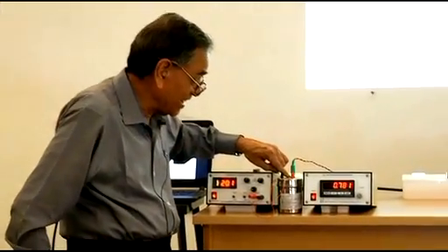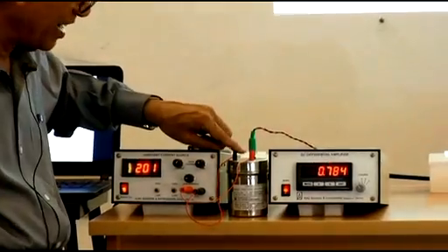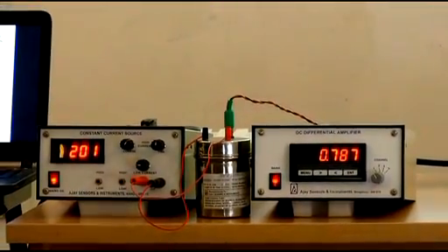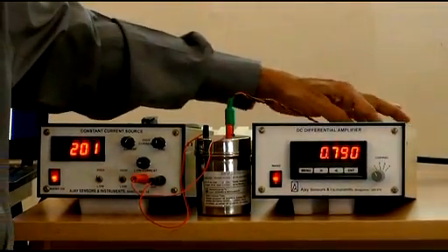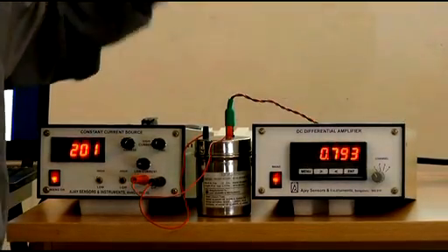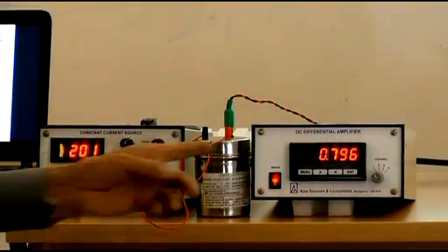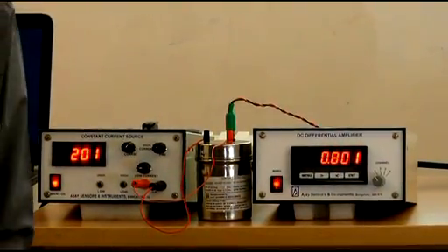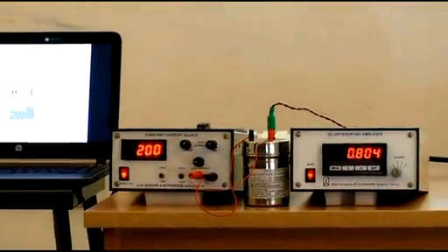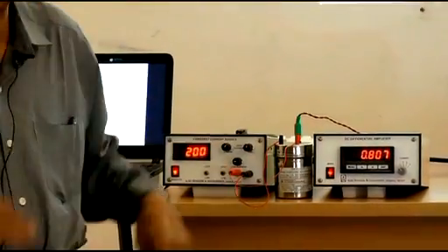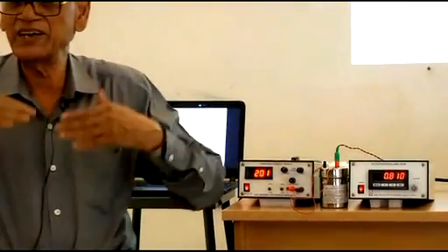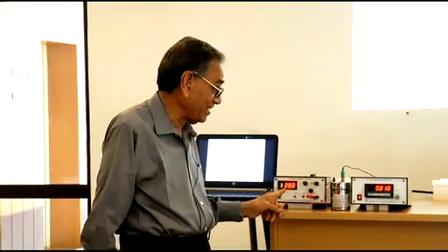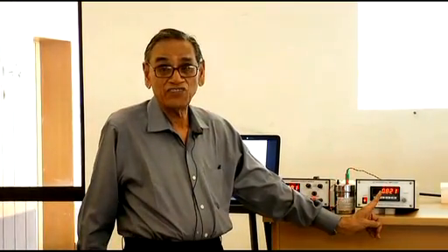The two thermocouple leads come to an RCA plug on the lid of the stainless steel box, and they are connected to channel 1 of the differential amplifier, which reads the thermo EMF in millivolts. You have to wait for 1 hour for this reading to reach a steady value. The reading will keep on increasing, and after 1 hour it will reach a steady value. Then note the current and the reading of the thermo EMF.